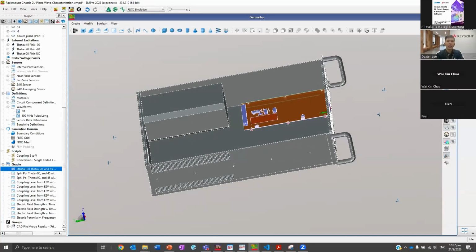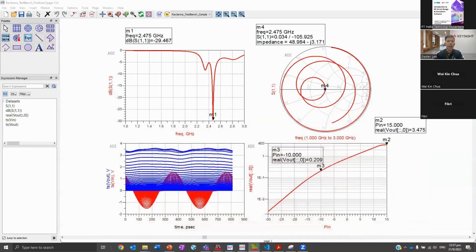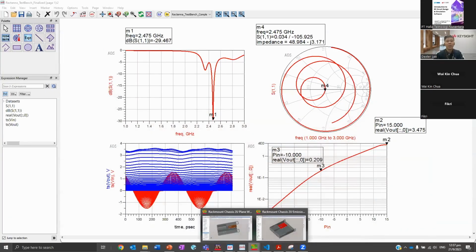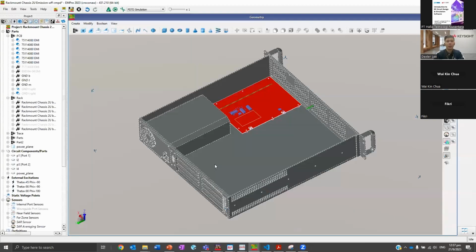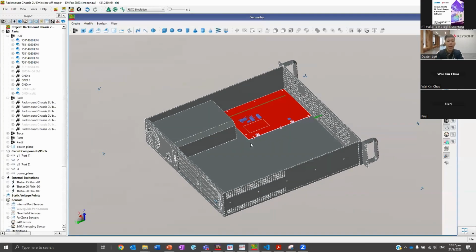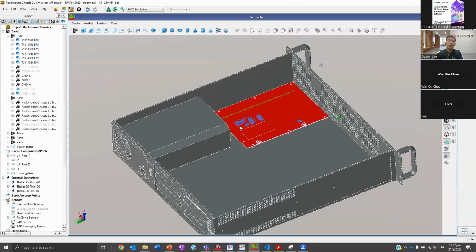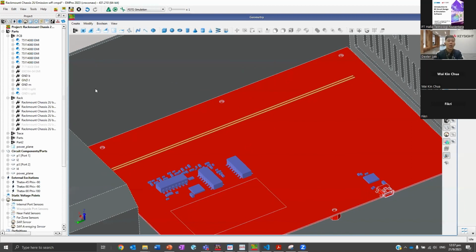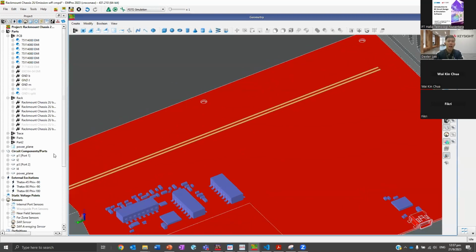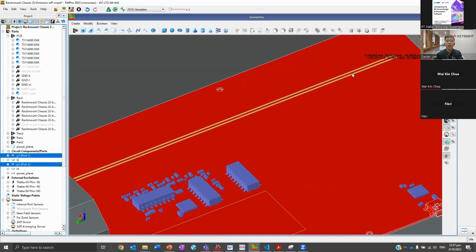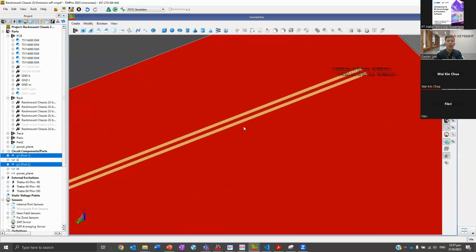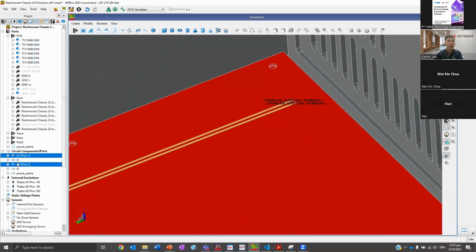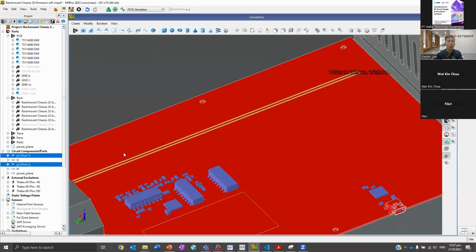The next part is on EMI, right? How much emission is being produced for this design here. So we can use back this same design here. And the main interest is this differential line pair. Okay, so what I've set up here is my ports. This is where my main signal will come in. And then I have terminated with a 50 ohm load here.